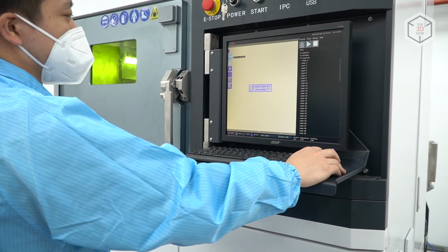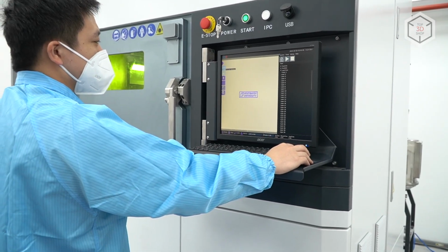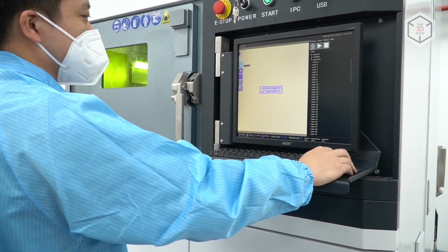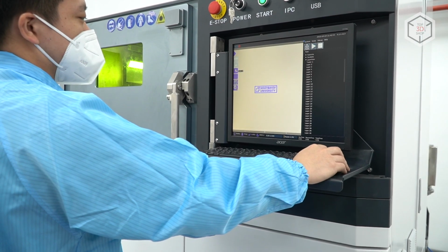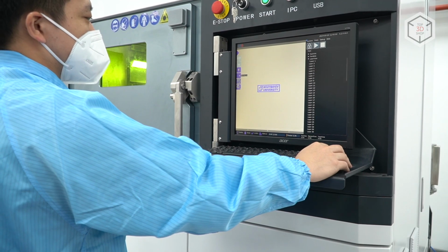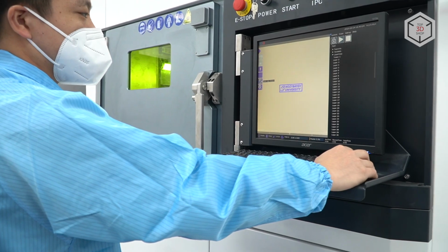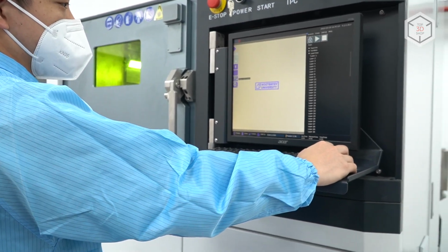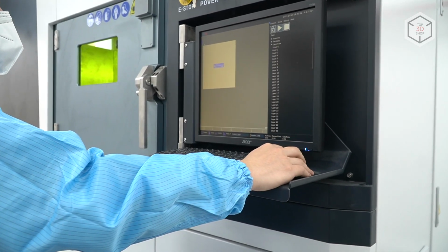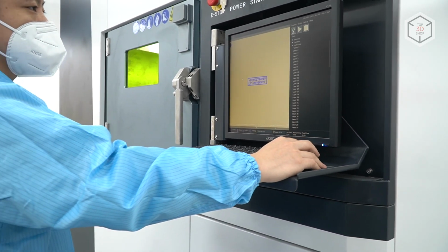In addition to this, we have the function of removing the oxygen, the auto new oxygen function, where we engage the external purifier. We have the function of starting the laser in order to launch the print, the function of turning the lights off in the build chamber, and turning on the heating of the build plate. The next function allows us to check whether the data has any problems. And the final one is to reset the view. So here we go back to our original view of the model.